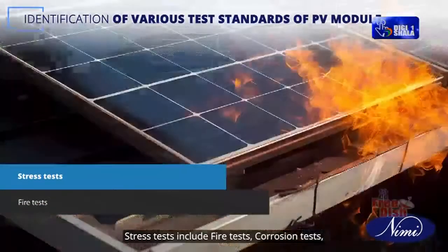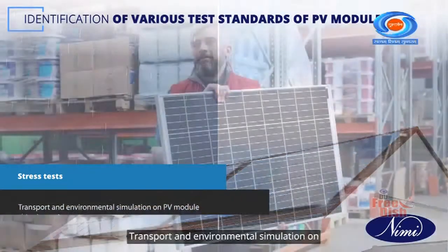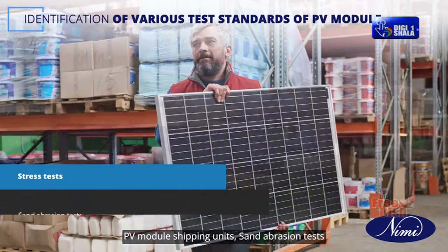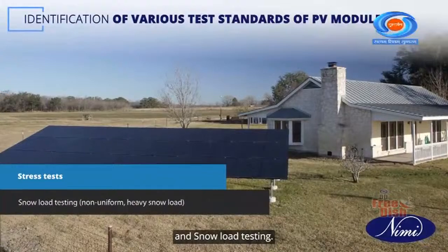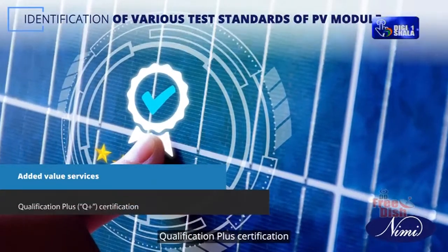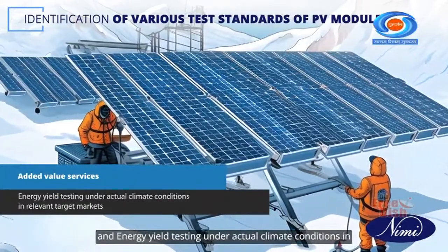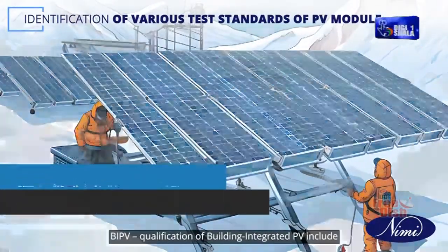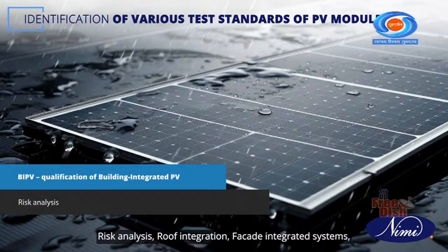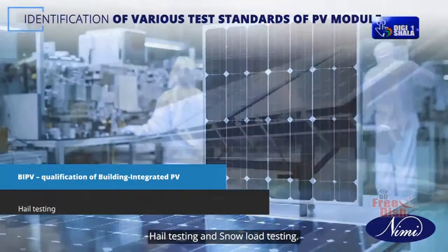Stress tests include fire tests, corrosion tests, outdoor long-term tests in different climate zones, transport and environmental simulation on PV module shipping units, sand abrasion tests, and snow load testing. Added value services are PV plus benchmark, qualification plus certification, and energy yield testing under actual climate conditions in relevant target markets. BIPV qualification of building integrated PV include risk analysis, roof integration, facade integrated systems, hail testing, and snow load testing.